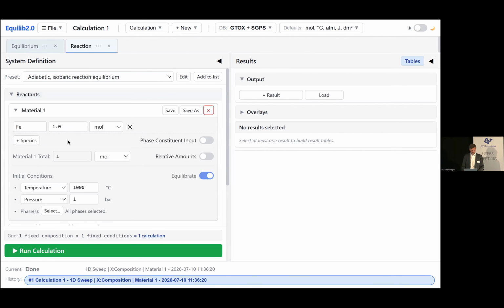Okay. Concerning the reactants input, if you care about reaction properties like the enthalpy of reaction and all of that, then you have to specify a bit of extra information concerning your reactants compared to just the system composition, right? You now have to say my reactants consist of this phase and that end member, yeah? Or you have to say my reactant consists of this composition in equilibrium. Yeah, and these are things that we have drafted here, how to do this.